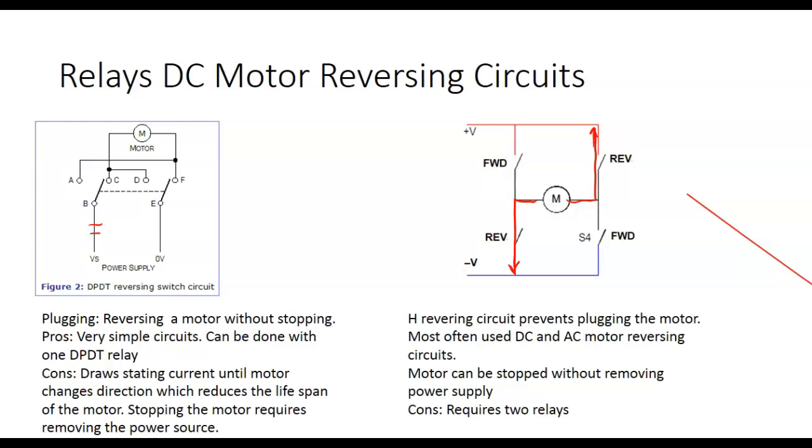So I've got two options here on this one. We could still plug the motor, right? Or we could put a timer in there, like James said. I've got a circuit over there on motor controls using a PLC. We don't teach PLCs over there. Eventually, hopefully, we will. We're trying to get the motor controls lab over here, by the way. So we've got a PLC running a three-phase motor, and we're just reversing it. We'll turn it off and let it time, and then we'll start it over.